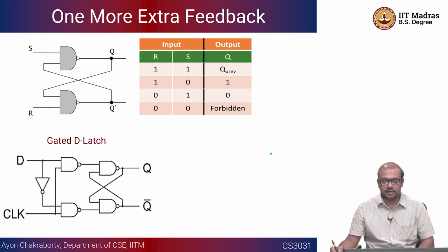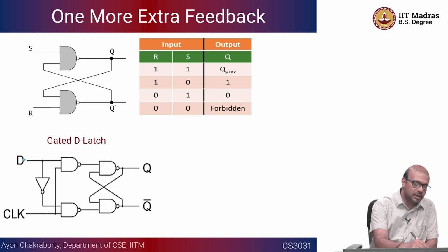That circuit was trying to bring back the lost input that we had in case of SR, because in SR you had two inputs, just that one input combination was not valid or forbidden. That was lost in case of D latch or D flip flop because of only one input. So this is the only input that could have been given here. It's the only input.